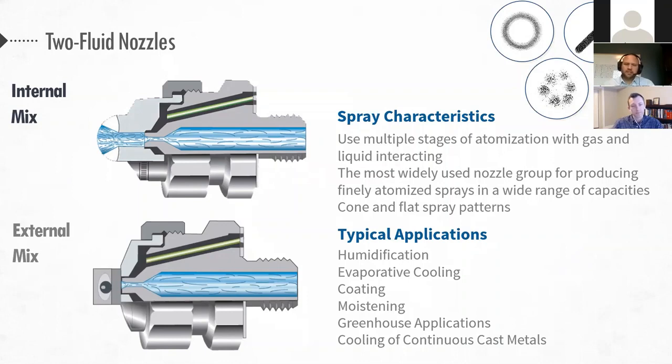And I've seen instances on the internal mix, let's say it's an SCR application where they use a lot of internal mix nozzles, but if there's a certain upset inside that pressure, it can actually vapor lock that nozzle, and you actually need a little bit more force to overcome to then start spraying. And so it's these little bitty insights that can go a long way, right? Getting environmental dings, because what we think a nozzle is flowing when in fact it's really not, is pretty important to know that you need to goose a little bit of that pressure to get it flowing again and then back it back down. But just understanding the mechanics of that can be very helpful.